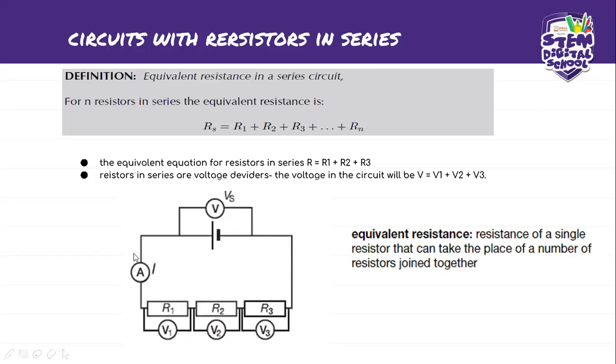Remember I told you guys that whenever you measure, this is your ammeter and this is your voltmeter. So this is not your voltage, it's a voltmeter. It's measuring the value of your voltage across the resistance. And your ammeter is not your current. It's an instrument used to measure your current, in series with the conductor. So whenever you place these two, you always put a voltmeter in parallel to the circuit and your ammeter in series to the circuit.